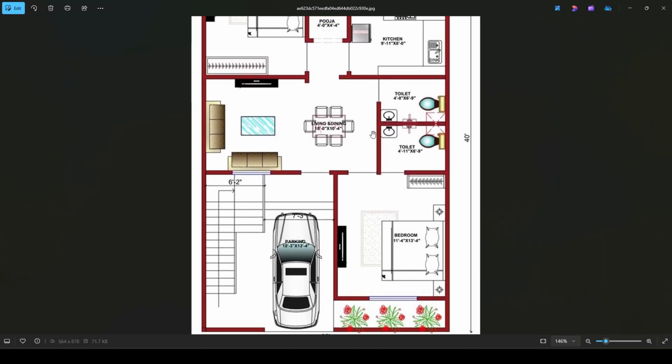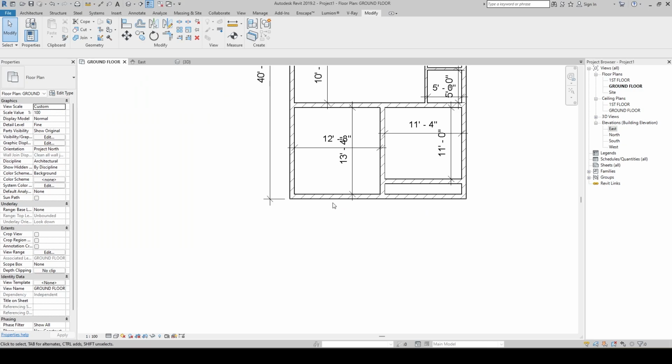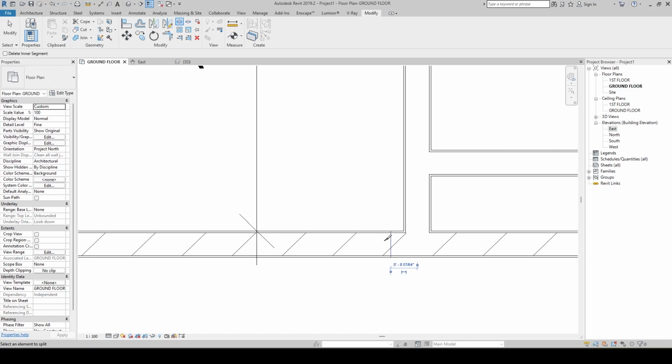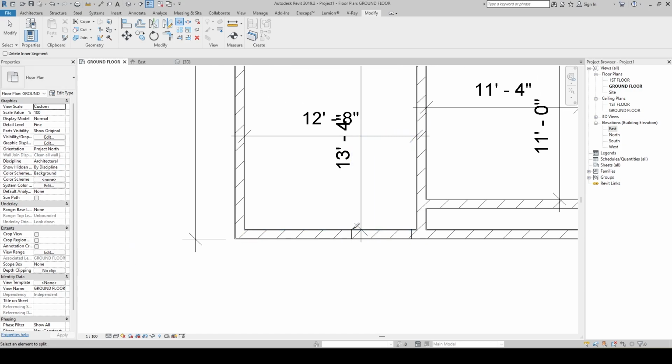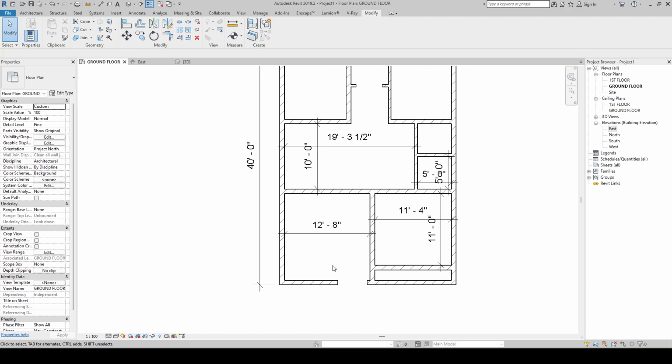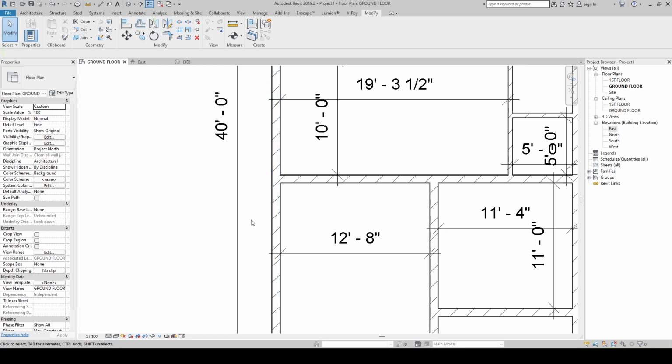In the front I think we need to open here. I'll open this here as well. I'll use the command split, SL. I'll take around 100 mm extra somewhere here and open this much. Select this and I'll delete, and I'll split from here itself, SL.